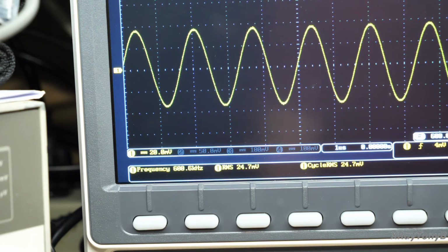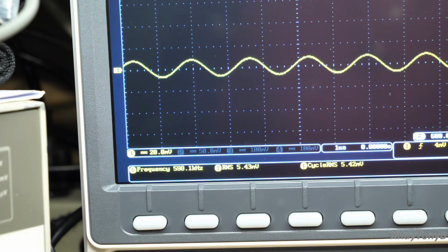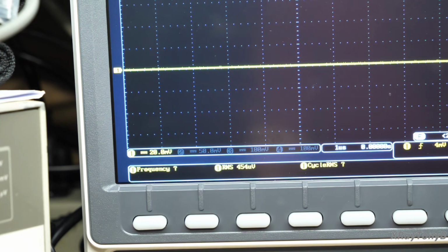Now, to go even further, let's say we go to a 20 dB attenuator, and you can see how tiny it is now. Now you're down to 5 millivolts roughly, okay? By putting that 20 dB attenuator in there, you are reducing the signal level by a factor of 10. So it's 1/10 of that. And the beauty of it is you can stack these attenuators together and add them up.